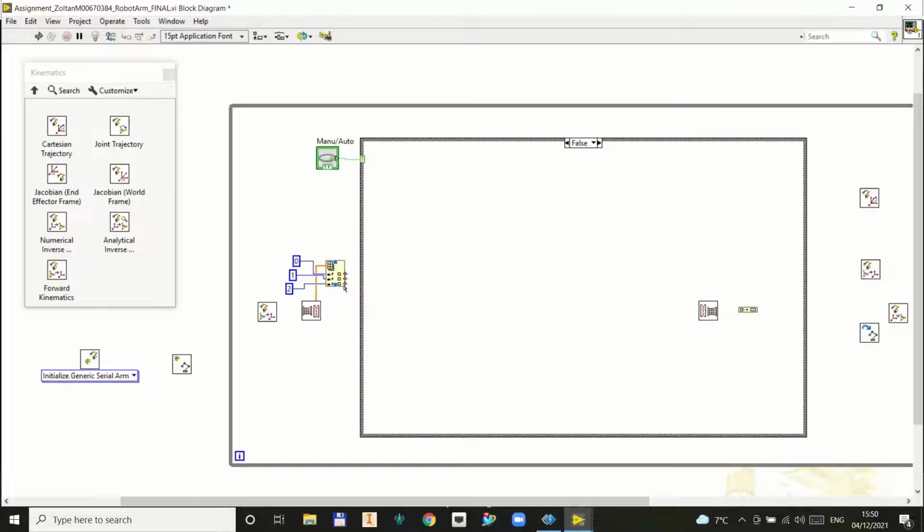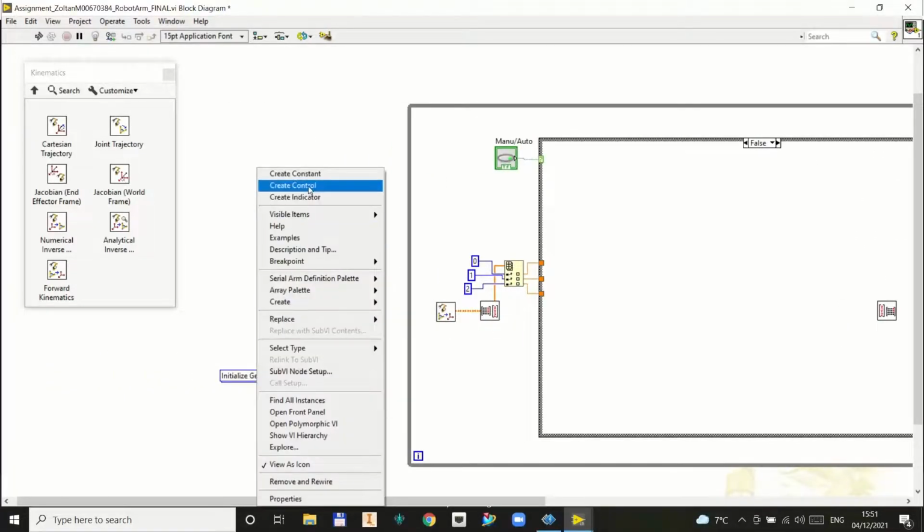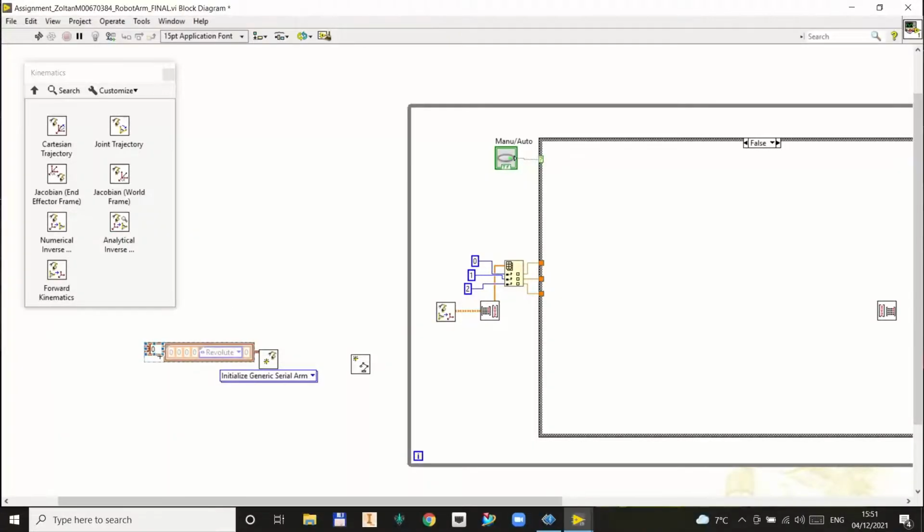The arm has 4 revolute joints. The first joint is responsible for moving along the y-axis. The second and third joints are responsible for manipulating the tool position on the x and z axes. The length between frames was chosen to fit the task of reaching the 3 shelves and the floor as well.